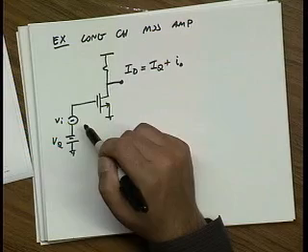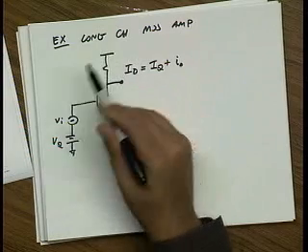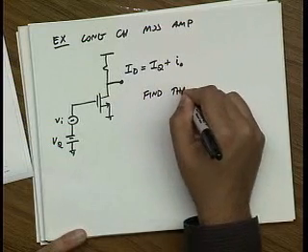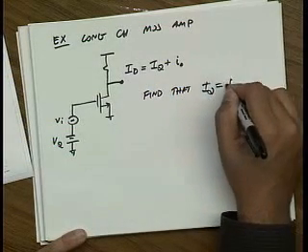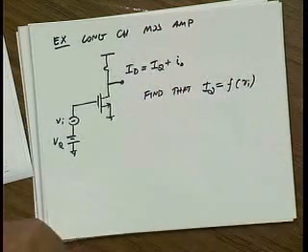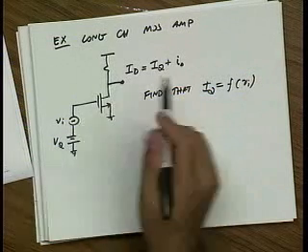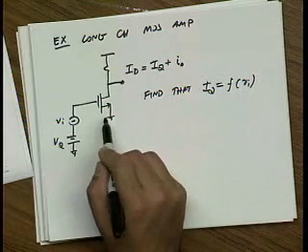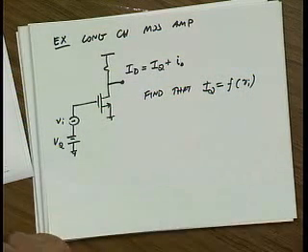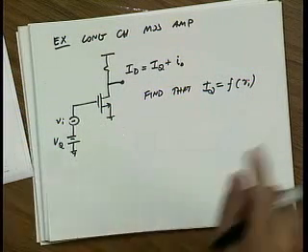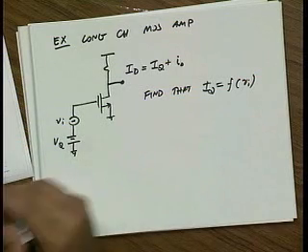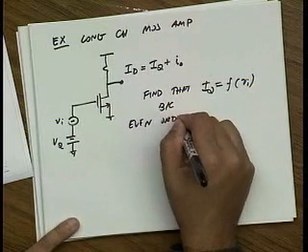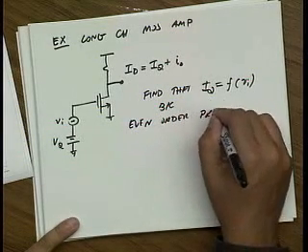If I had just a simple system like this, I would find that IQ is a function of V input. So I couldn't just simply take it out of the equations like I usually do. Remember, cosine squared is 1 plus cosine at twice the frequency. So that one term generates DC. So even order produces DC.